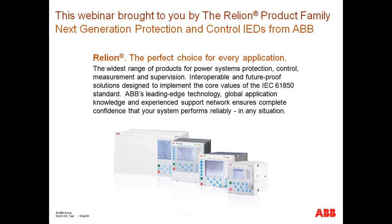Good question. I have a question here that says, how does GOOSE go from one remote location to another for a transfer trip without being part of a routable protocol? That's an excellent question. In the applications where we've seen this applied, you actually have a direct fiber network from one substation to another substation. It could also be packeted as part of SONET, if a SONET communication ring exists within the substations. But GOOSE itself is a layer 2 protocol, so it's not dependent on IP addresses.